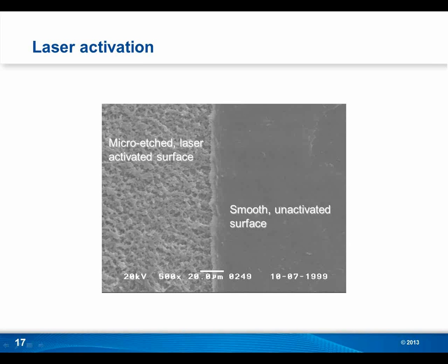In two-shot molding, a lot of times you have to add a chem etch step to get some roughness, so that your plating will actually hold to that surface. You get rid of the smooth mold skin. The nice thing about laser direct structuring is that within the activation process, in a single step, you actually roughen up the surface also. So you get a very strong adhesion to the plating and a very, very high peel strength. Gotcha. Getting that peel strength is really important.